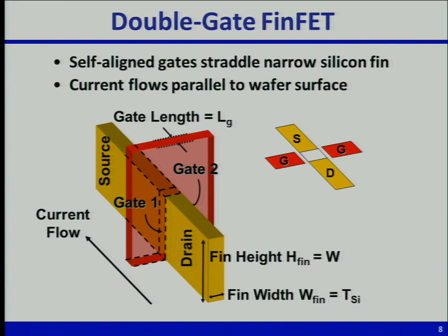And you have current flowing on the side walls in the on state and in the off state. The taller the fin, essentially the wider your transistor is, and the more current you can flow. So that's basically the difference. Here's the SOI FinFET. I'll pass it around just in case you have a hard time visualizing, but this is the conventional planar MOSFET if you want to compare.